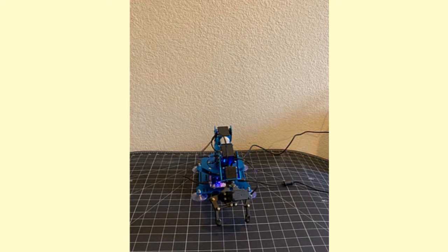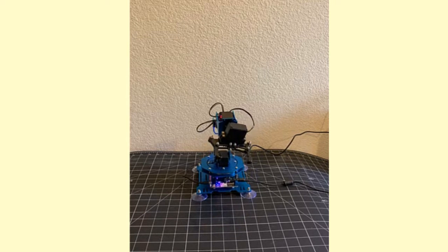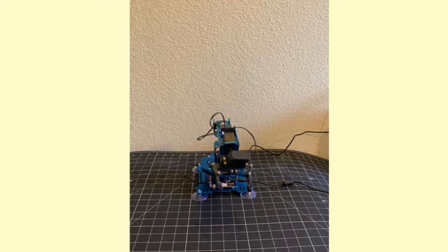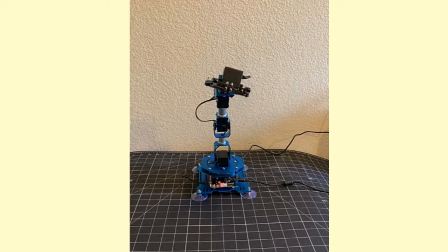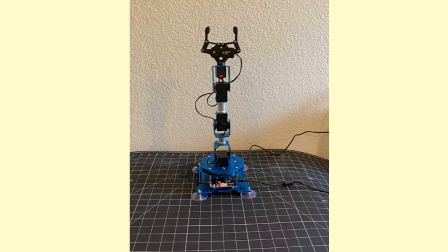Now let's move up back to its normal position. So to do that, let's actually tune our servo 5 first, because it actually is a lower servo. Now 4. So when you do reset, please go from the bottom servo first, and then control servo 3. Now it's almost back to the upright position.